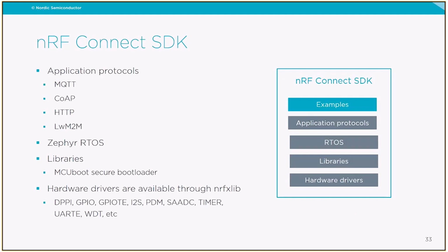So the nRF Connect SDK has the different application protocols: MQTT, CoAP, HTTP, lightweight machine to machine. It includes the Zephyr RTOS, and also the different hardware drivers: GPIO, I2S, SAADC, timer, UART, watchdog timer, etc.